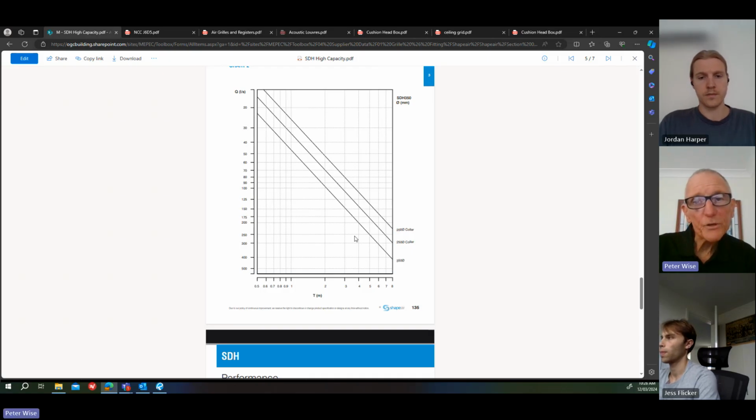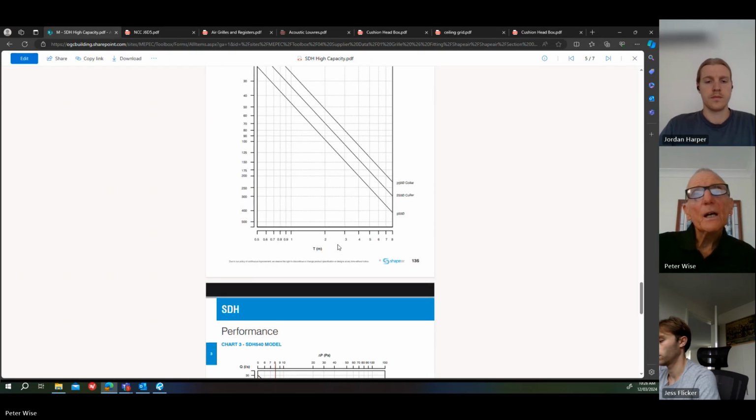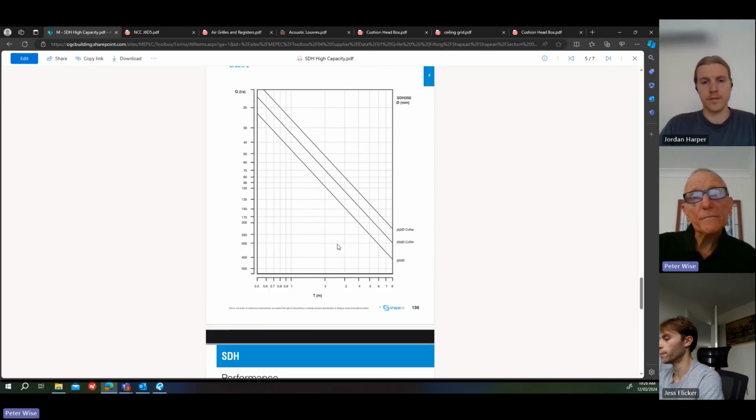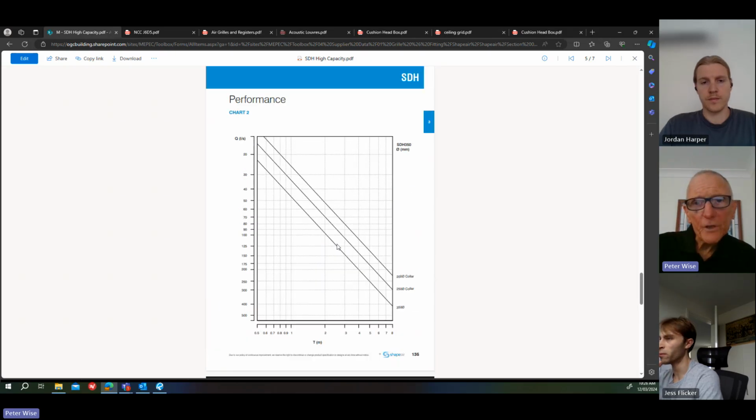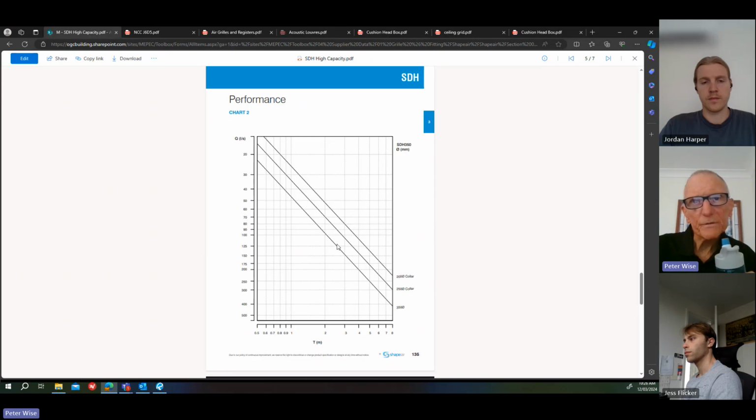You'll need more swirl diffusers to get the same air distribution. But the air distribution will be better. You get better induction. And as I said earlier, they work better for variable volume systems where the airflows are reduced and you don't get the dumping that you'll get with a louver face. So they're probably the main considerations there when you're looking at the comparison between the two.